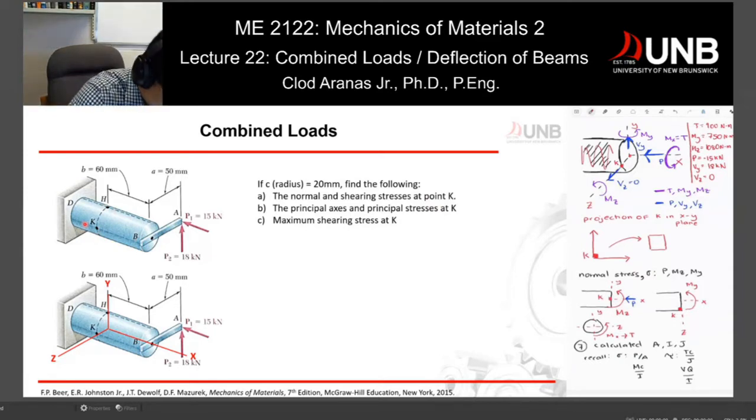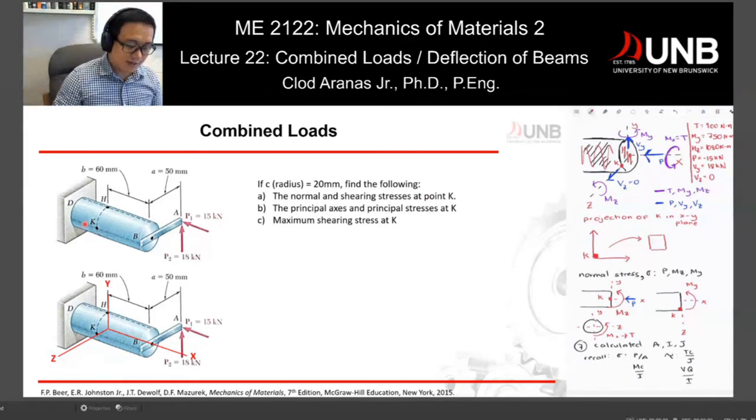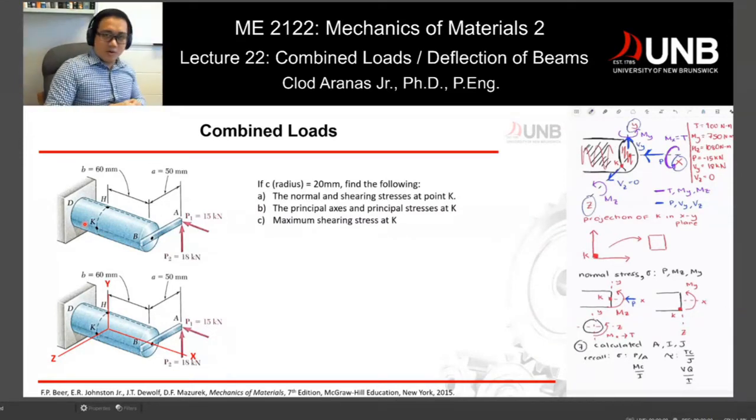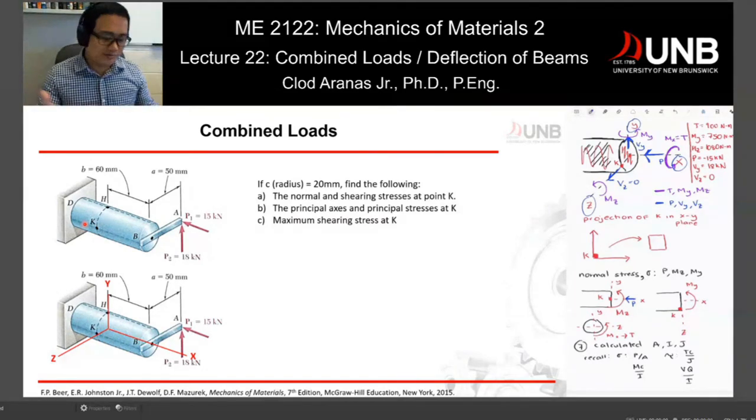So now we have this cross-sectional area. Now, once we have a cross-sectional area, you have 3 different forces aligned along your X, Y, and Z. So that's your X, Y, and Z. Now, you also have moments along those axes. So technically, you have 6 numbers that you have to think about, and what would be the effect of those on normal stresses and shear stresses.